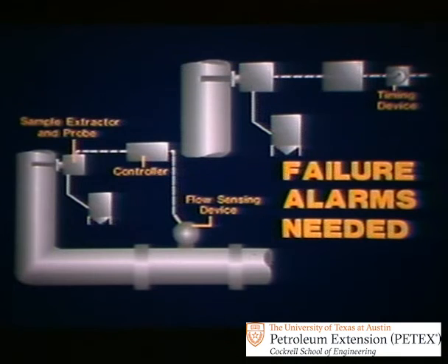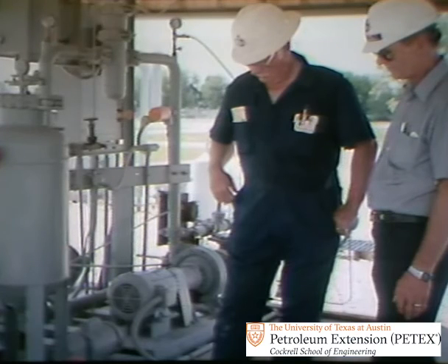Whether flow proportional or time proportional, failure alarms are needed for any automatic sampling system. Otherwise, non-representative samples, or no samples at all, may result. And finally, remember that there's no substitute for vigilance on the part of personnel in case the alarm system fails.